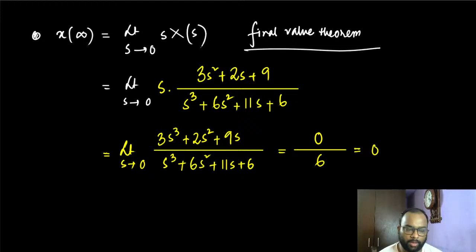All right, so we're going to do a complete example once again after we discuss all of that. So this is your final value theorem. One of you is asking, how would you know that we have to use the final value theorem? So you would know that you want to use the final value theorem when you don't want to actually do the inverse Laplace transform. See, when we applied the final value theorem, we calculated the final value of x(t) without actually calculating x(t).